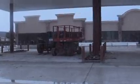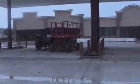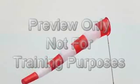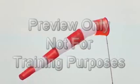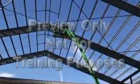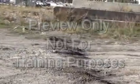The potential risk associated with weather conditions must be addressed and controlled. MEWPs must not be used outdoors in thunderstorms or when the wind speed exceeds the maximum allowed by the work platform manufacturer. Be aware that equipment and supplies on the work platform can act as sails in windy conditions. Poor ground conditions, such as subsurface voids and inadequate outrigger foundations, can cause instability issues which can be very dangerous. Potential ground condition hazards must be identified and addressed.